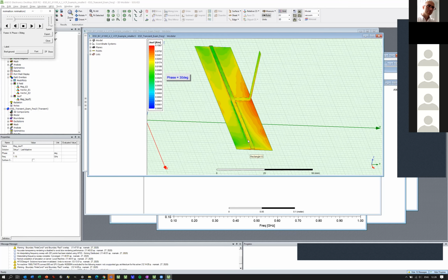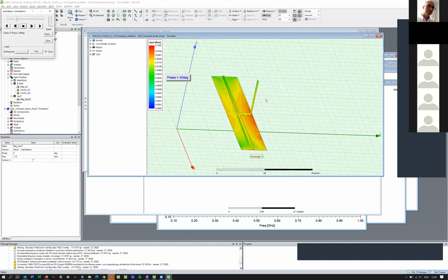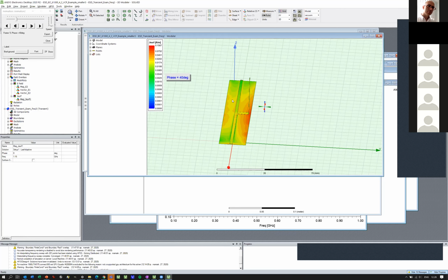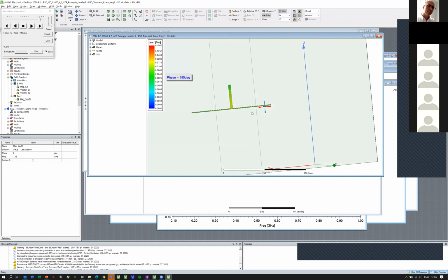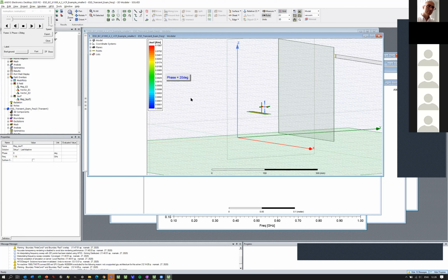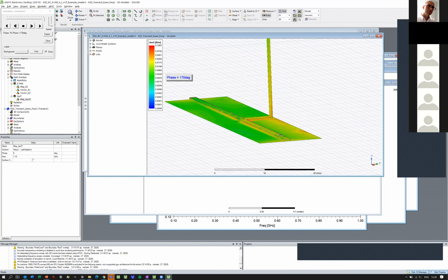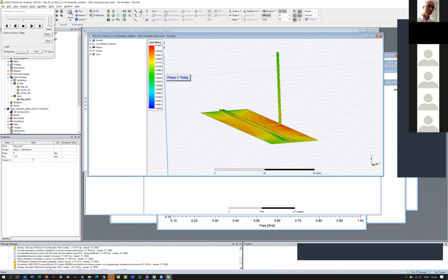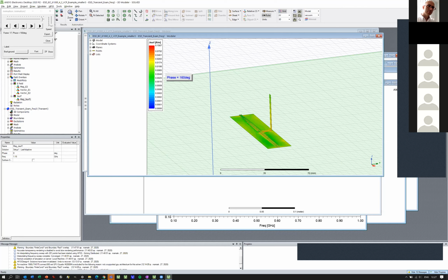So we have 50 ohm termination on both sides, and you can see that a lot of energy is coupling to the antenna because it's at 90 degrees. So it's a receiving antenna for any field radiated by the metal plate. And it will couple onto my circuit board and, in the worst case, cause immunity issues with my IC. So I have 2 options. I can seal the antenna with metal or EMC sealing, or I can have filters here to block the signal from coupling inside.